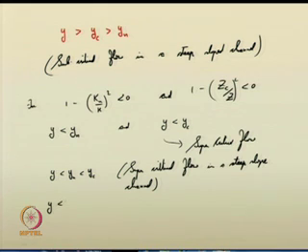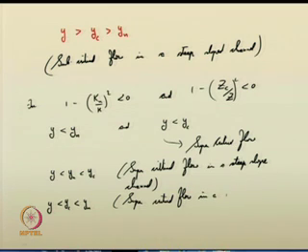For y less than y c, but less than y n, this implies supercritical flow in a mild slope channel. Similarly for the drawdown curves, dy by dx has to be negative, and the further classification of the gradually varied flow profiles we will discuss in the next class.